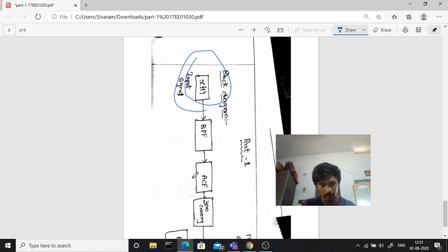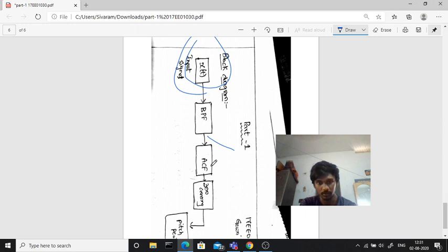Then we apply the autocorrelation function. Autocorrelation is a correlation of a signal with a delayed copy of the signal itself. So it generally smoothens the signal of our system. Then we have the zero crossing point. The zero crossing point is that we measure the